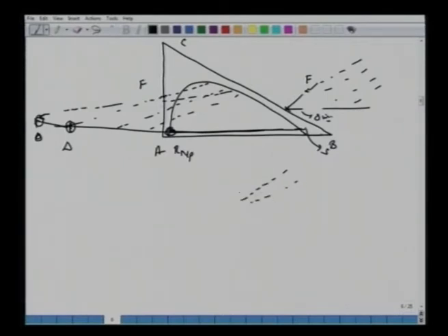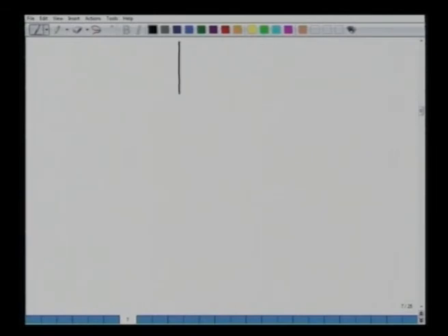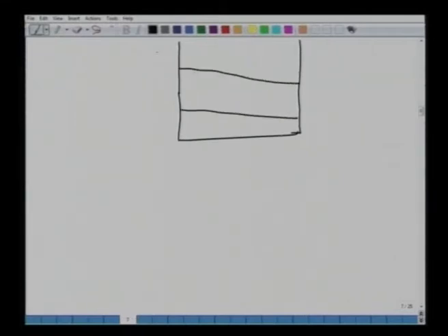If you recall, we had equilibrium curve HV, HL, and we said to find out this minimum amount of reflux ratios, if this is a location for feed, then find that tie line which extends here. This gives us R min, and then there is a possibility that in certain non-ideal systems, certain other tie lines which you extend will give you R min. So we have also a similar kind of situation in case of extractions.